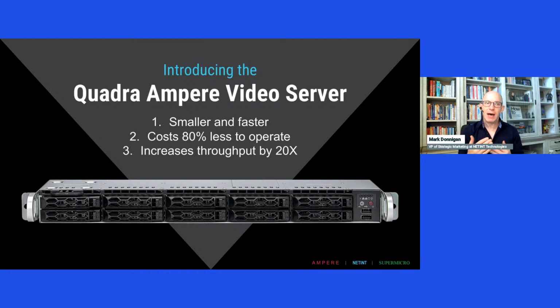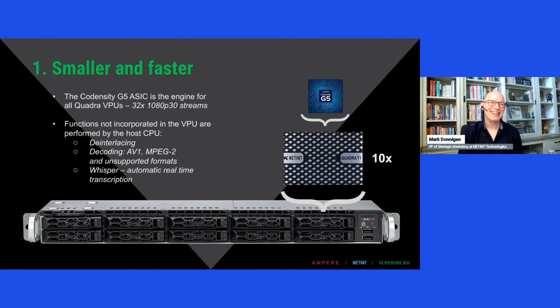You're going to get about 3 to 4x lower throughput with HEVC. And then when you go to AV1, it's even another 2 to 3x lower throughput than HEVC. So it always scales down. With ASICs, it scales perfectly linear. It's perfectly flat. So the performance curve, the density curve, is the best.